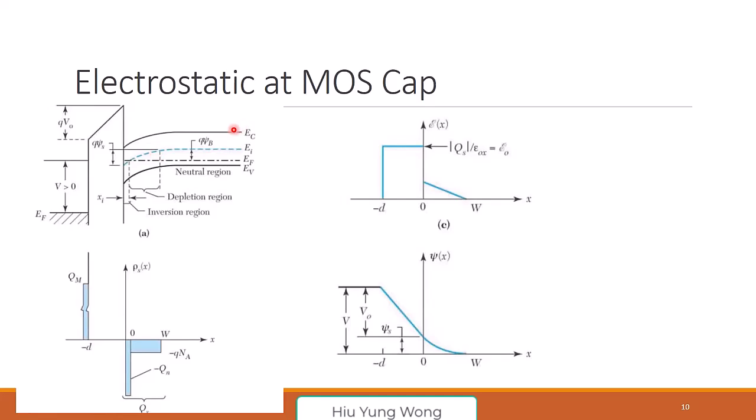First of all, tell me what is the substrate? Is it N-type or P-type? P-type. P-type, because? Fermi level is close to valence. Thank you. Fermi level is close to the valence band, so you don't have much electron in the conduction band, right? Because again, the Fermi-Dirac distribution tells you that the tail is very small, so you don't have much electron there, but you do have some hole in the valence band. P-type.